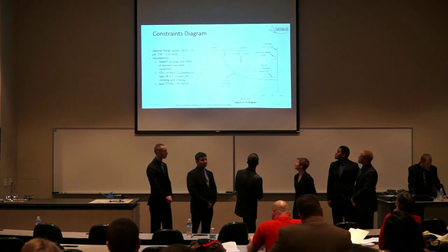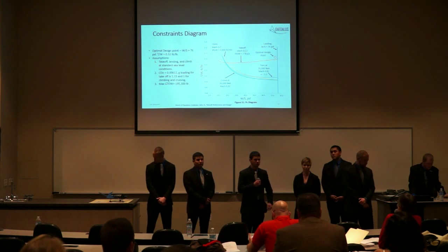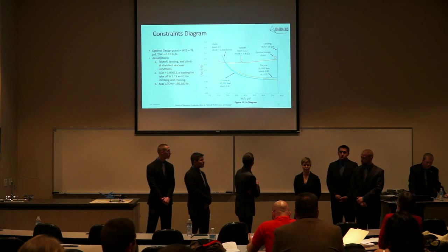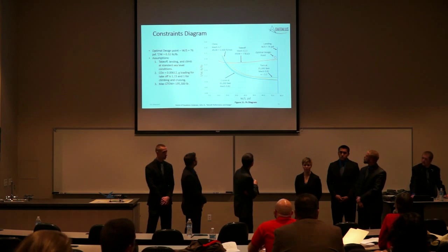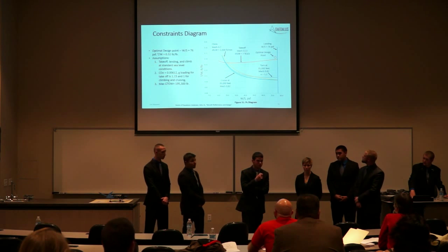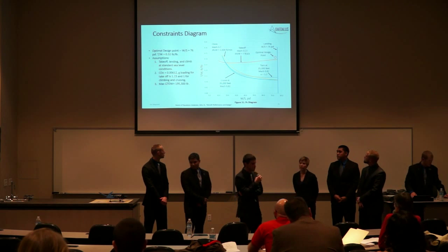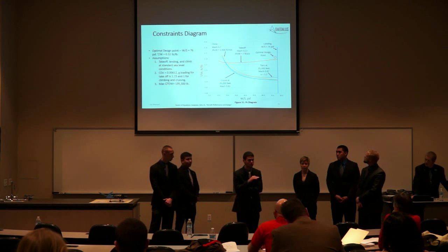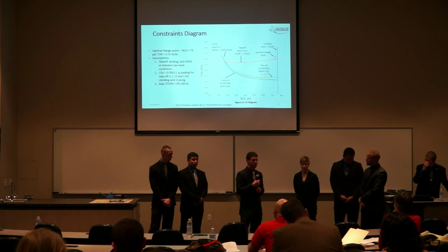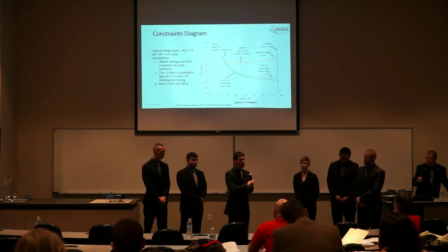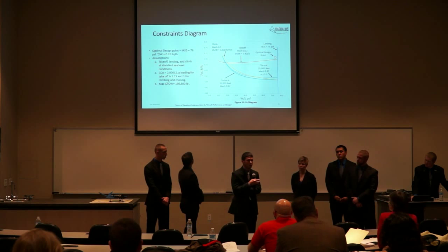Okay, so that's your constraint, and it's pretty big compared to everything else going on. What's the driver of that particular line? The takeoff parameter? Well, the takeoff at Mach 0.22. That's at sea level with the stall velocity, or just above the stall velocity, so it could rotate and take off. That was why it's a little higher. And I assumed a G of about 1.15.